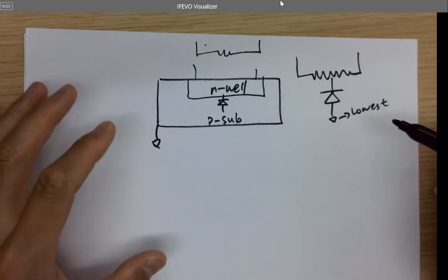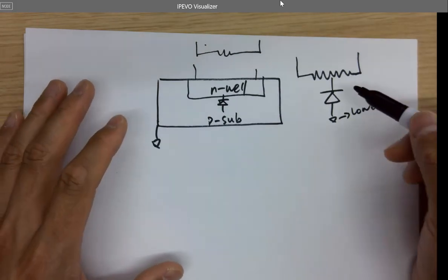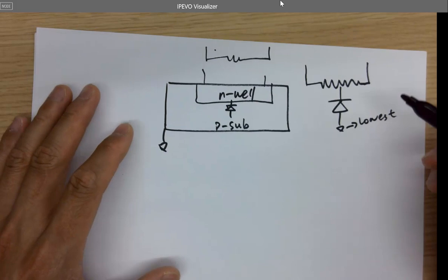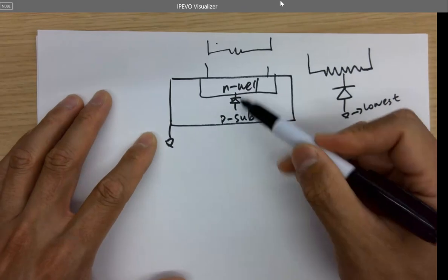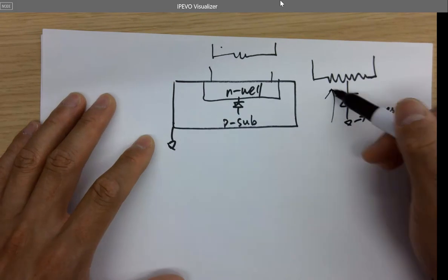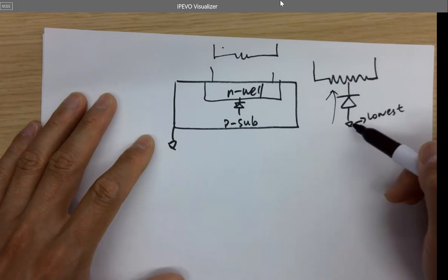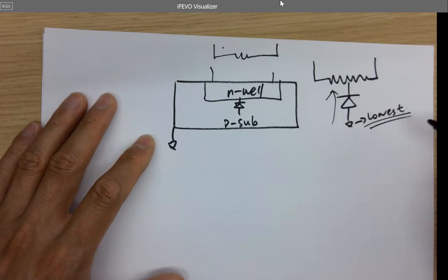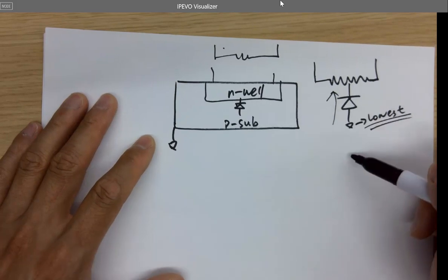It's gonna work. I put it on the tutorial, it's gonna work, right? Otherwise, I won't put it on the tutorial unless you lay it out. So there's nothing wrong with it. It's just a PN junction. There won't be any current flow into it because I short the P-sub to the lowest potential in the circuit. And now it makes sense why we have to do it.